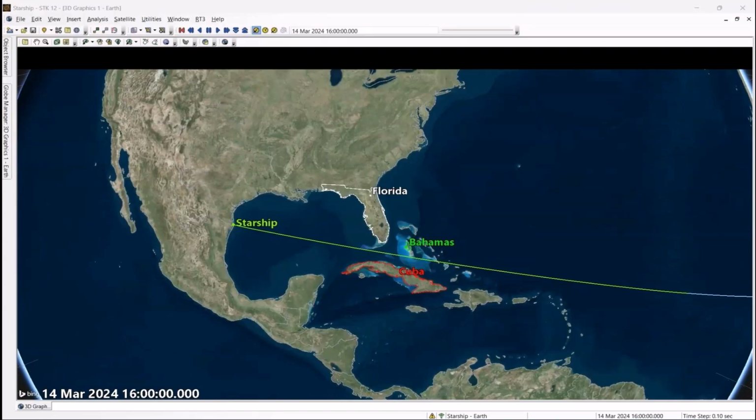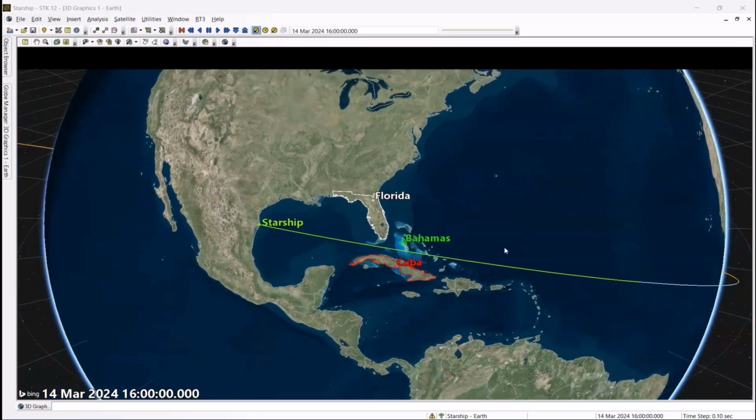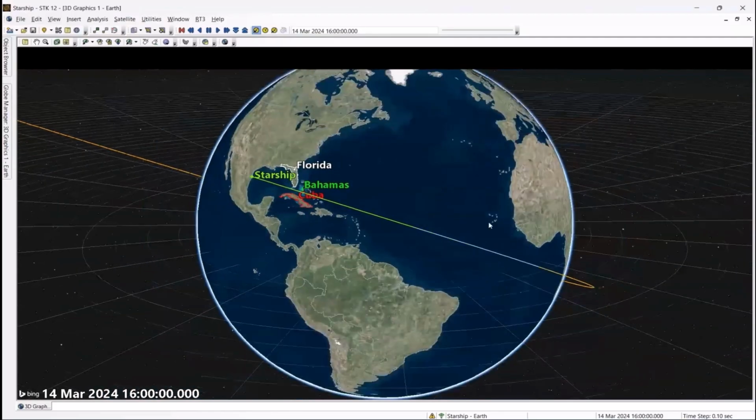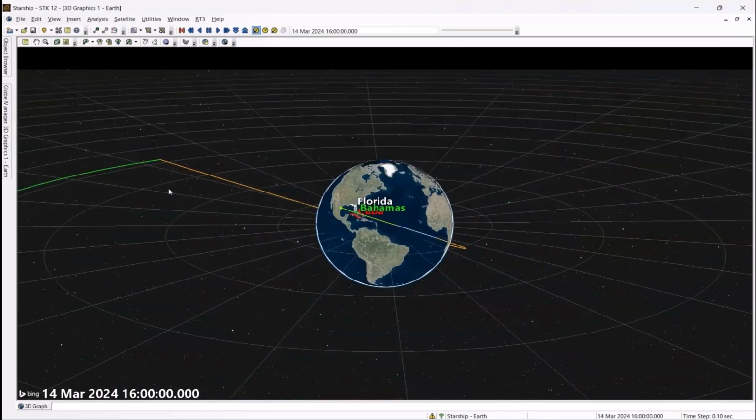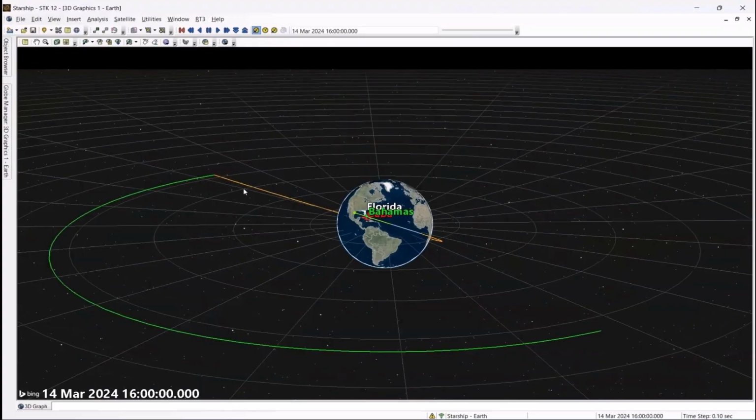The main constraint being the launch angle, which must take place between the southern tip of Florida and the northern tip of Cuba, and fly carefully in between the Bahamas Islands. So we need to reduce the access duration to this airspace to the minimum, to 0. And while doing so, it will be nice to be able to analyze which trajectory plan will be the best to optimize our next maneuvers, which are essentially a GTO maneuver and a change of plane maneuver in order to get to an equatorial plane.